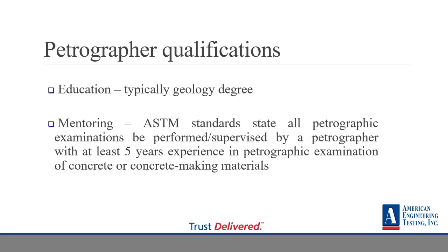So typical petrographic qualifications are an education, a degree in geology, typically. I say typically because I have met some engineers that do petrography. And then mentoring, which is, the ASTM standards state all petrographic examinations be performed or supervised by a petrographer with at least 5 years of experience in petrographic examination of concrete or concrete making materials.